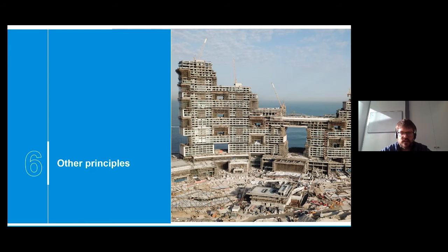And we did two different mix designs, one for the summer, one for the winter, because we knew that during the winter, when it's 15, 20 degrees outside, we were able to use a cement that was going fast. So we were using a CEM1, a sulfate resisting CEM1. We needed to go fast, and because it was quite cold outside, we wouldn't have any problem of temperature in these blocks. On the other hand, during the summer, when it is 50 degrees outside, we were using a mix with a lot of GGBS because we knew that the concrete was going to be really hot and go too high in temperature. So it's really a winter and summer mix design.